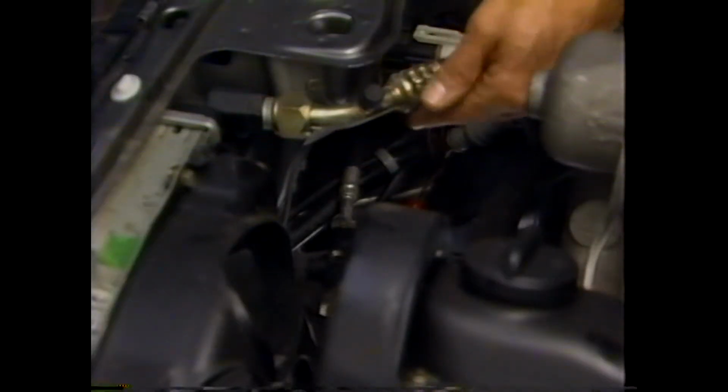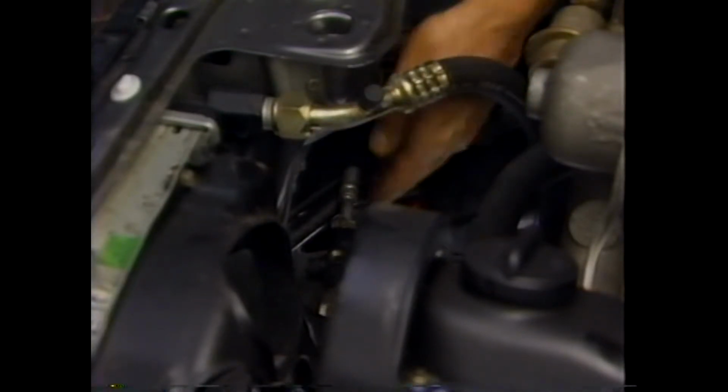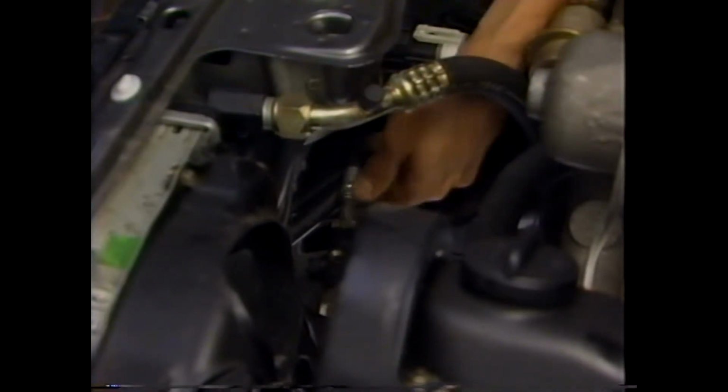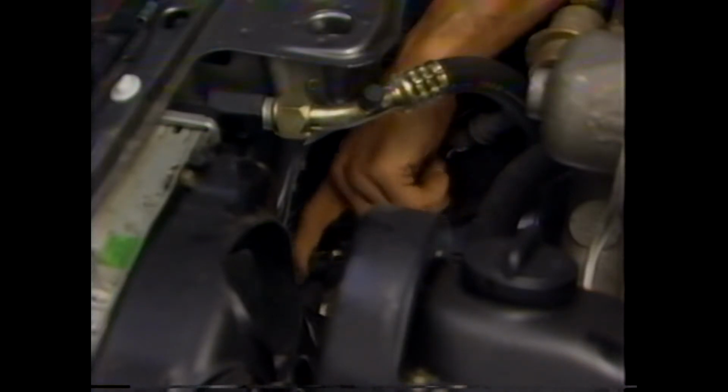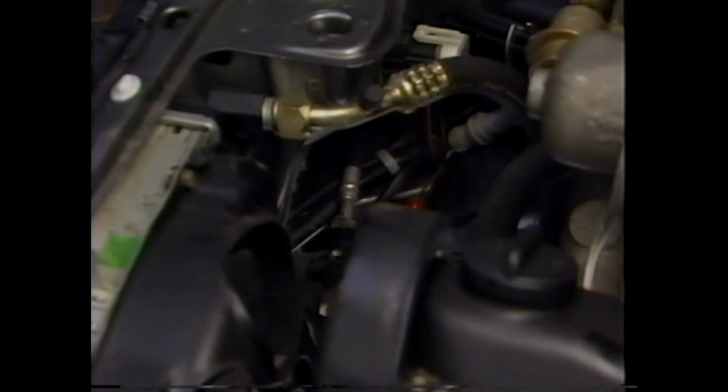Check the condenser for blockage or damage to the fins that could affect airflow and heat transfer. Inspect refrigerant hoses for damage and check all connections for obvious refrigerant oil leaks. Check the blowout plug on the receiver dryer. If high side pressure has been excessive, the plug will be blown out, causing a complete loss of refrigerant charge.